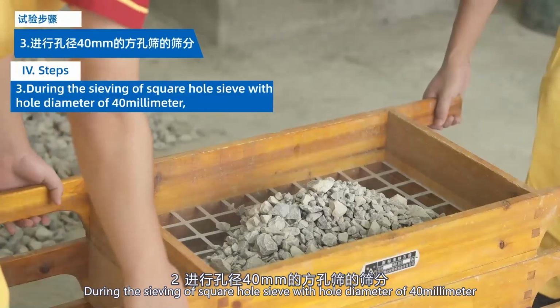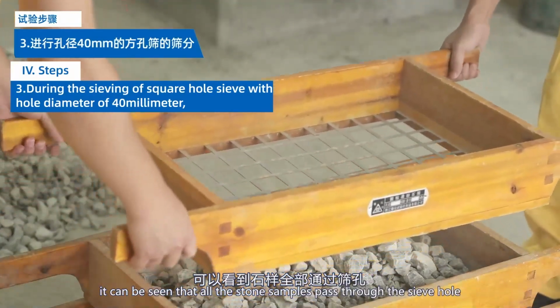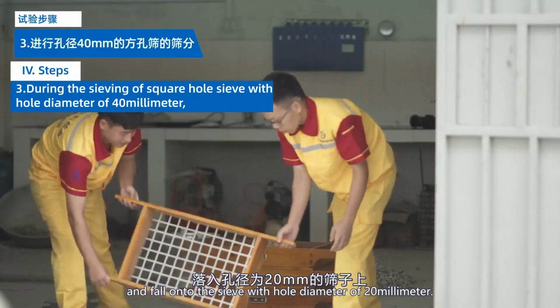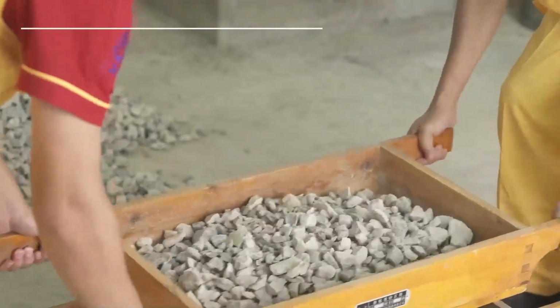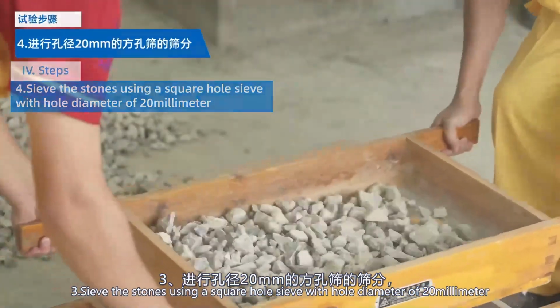2. During the sieving of the square hole sieve with hole diameter of 40 mm, it can be seen that all the stone samples pass through the sieve hole and fall onto the sieve with hole diameter of 20 mm. 3. Sieve the stones using a square hole sieve with hole diameter of 20 mm.